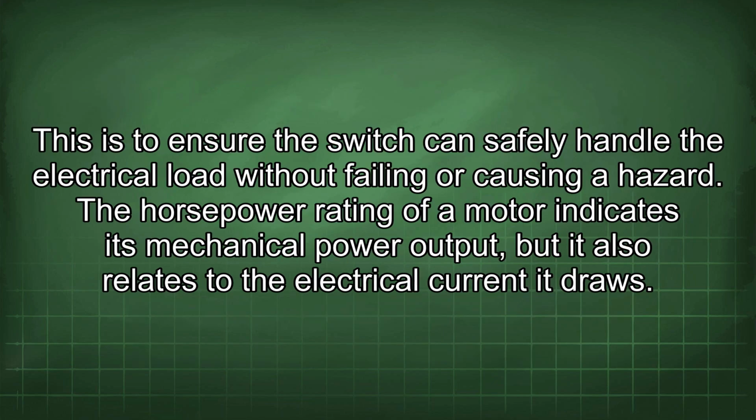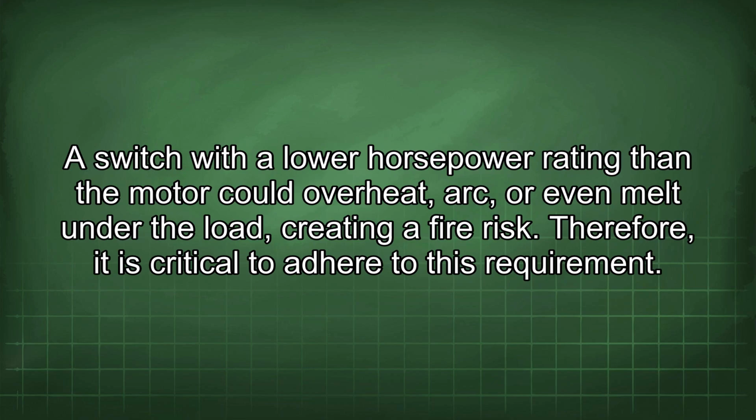This is to ensure the switch can safely handle the electrical load without failing or causing a hazard. The horsepower rating of a motor indicates its mechanical power output, but it also relates to the electrical current it draws. A switch with a lower horsepower rating than the motor could overheat, arc, or even melt under the load, creating a fire risk. Therefore, it is critical to adhere to this requirement.